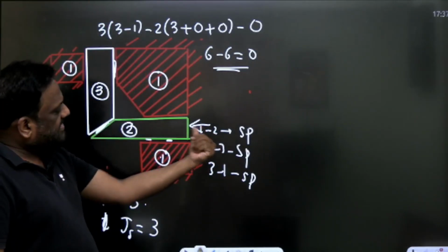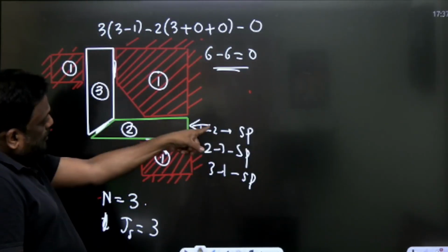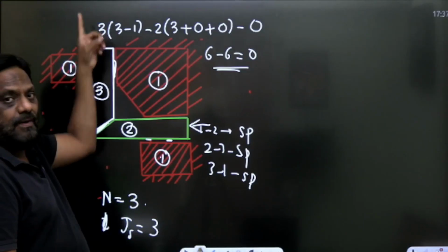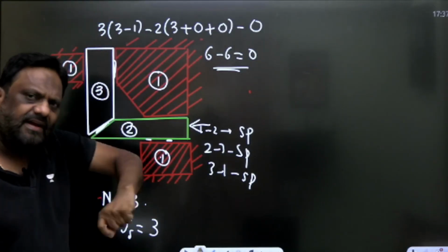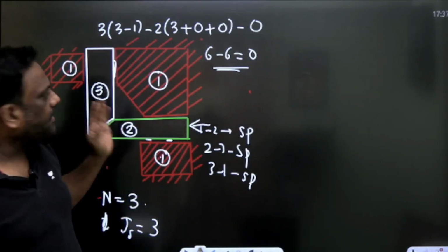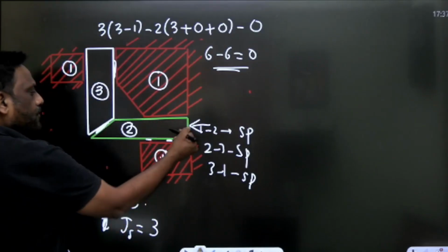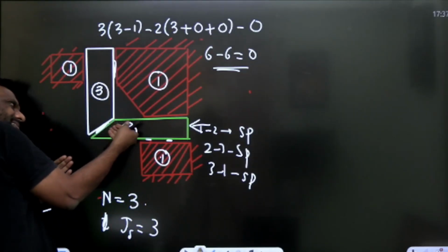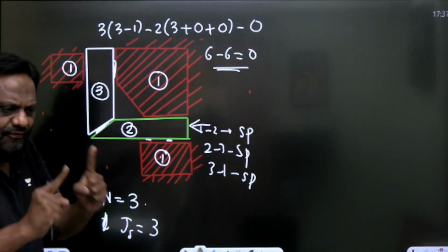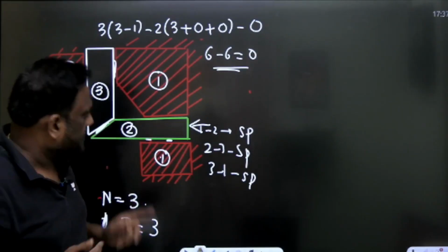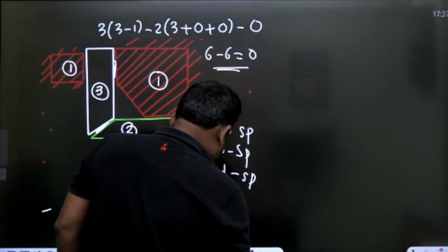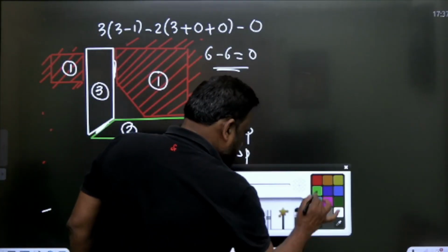If I move this some x distance, exactly corresponding to that x, there is one-to-one correspondence. Exactly that much output will come. So definitely the degree of freedom is one. So in this it is sliding. So here it slides from here and moves up. So the degree of freedom must be one. So how do we explain this? Look, now the explanation is something like this, my dear students.